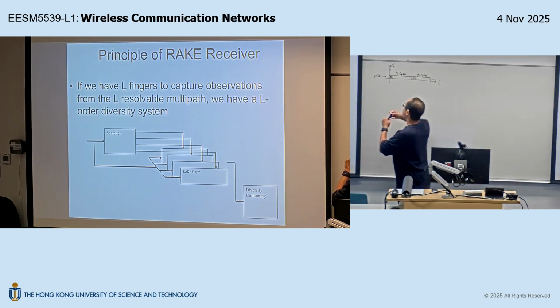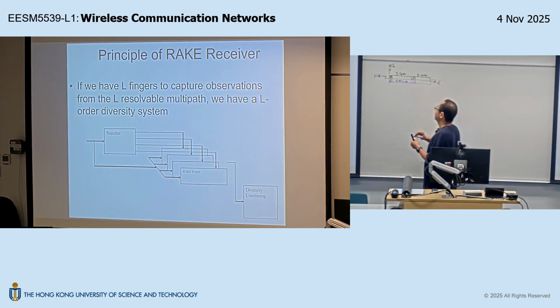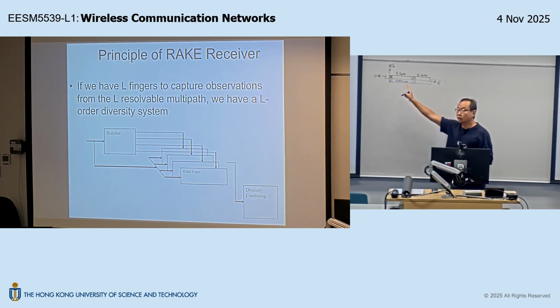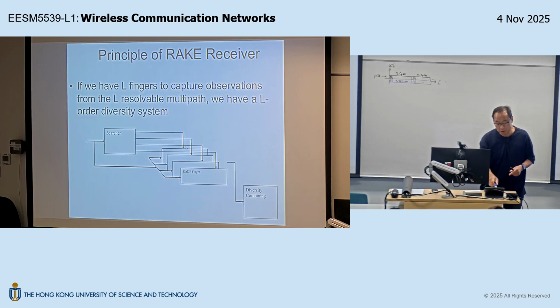For example, if this is the traffic channel to a certain user, S1T, C1T, the first chip of the data channel transmitted to user 1 will be aligned, synchronized with the first chip of the pilot channel. The data channel contains useful data, but the pilot channel doesn't have any data. It's just a fixed data pattern, let's say all 1.